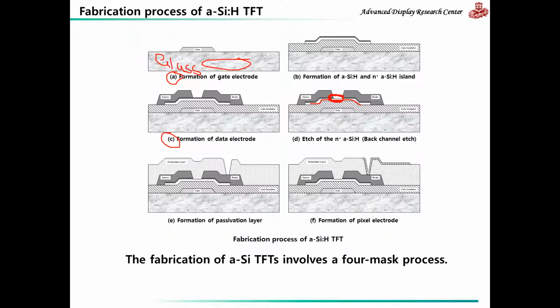Now, in order to protect the TFT from outside elements like the humidity or air, another dielectric layer is deposited on top of the device as the passivation layer. And finally, we form a contact hole, which is used to contact the drain electrode to the pixel electrode.